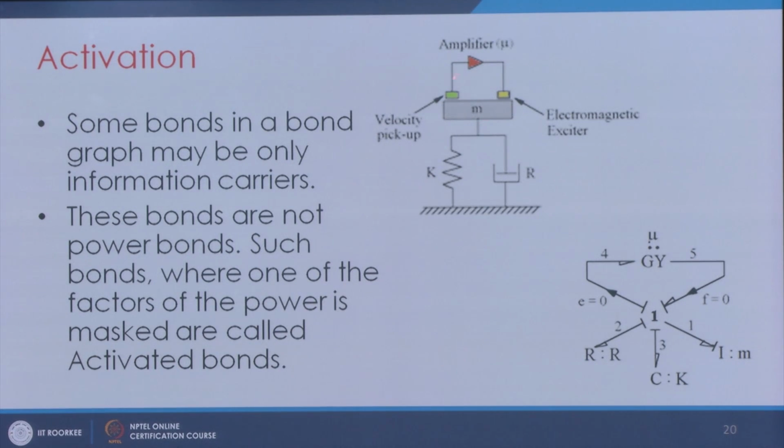So, to model this entire system, we take a one junction representing the velocity of the mass, and the other ends of the spring and damper are fixed. So, they will have 0 velocity. So, here I just put I inertia, then spring and damper, and here you see that what we are seeing is basically a velocity or flow being converted into effort. So, we can use a gyrator element to model this type of system.